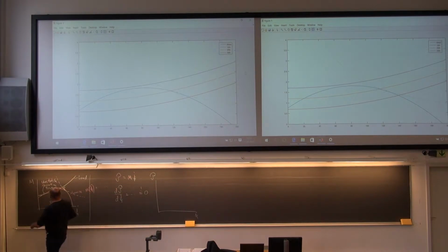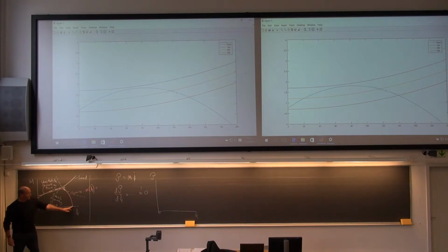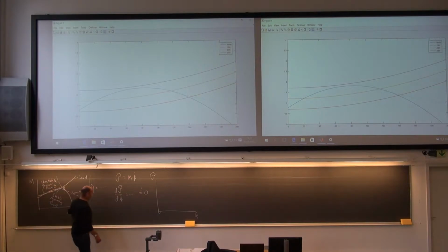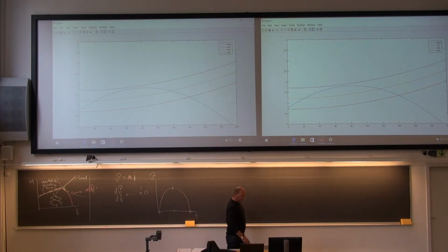Well, you start here, you have torque, but you have 0 rotation, so it will start with 0. Also here, you have a lot of rotation, but no torque, so also 0. And then the curve will look something like this. Then it's fairly easy to find the maximum power, at what rotational speed we find the maximum power. That's another way to do it. Okay? So that was just for a show.